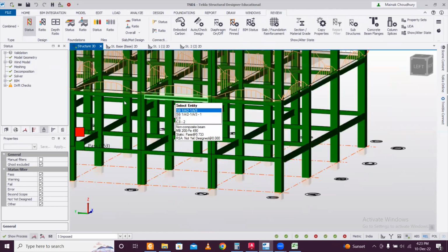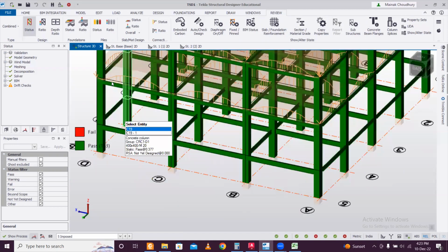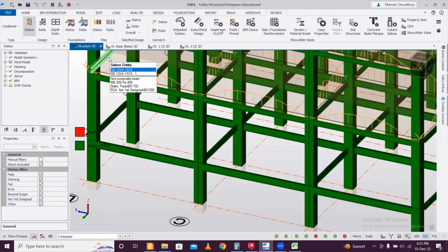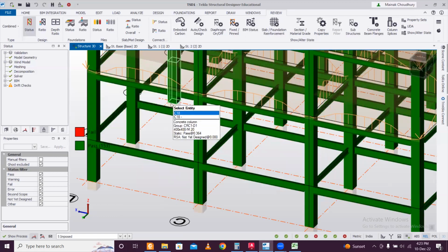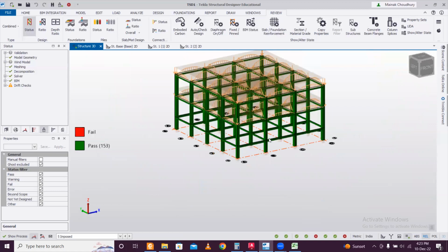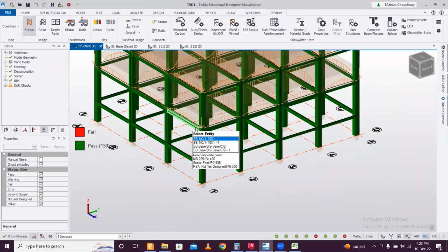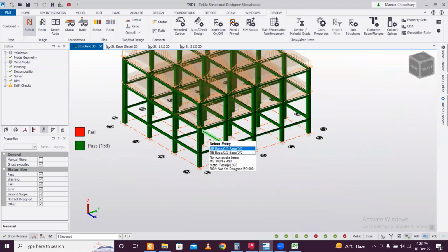So what you need to do is manually provide a uniform type here. If you decide like 250, then I've made every beam 250. So the software is not that smart. You have to decide on that, or you can turn off auto design, and then I can check.